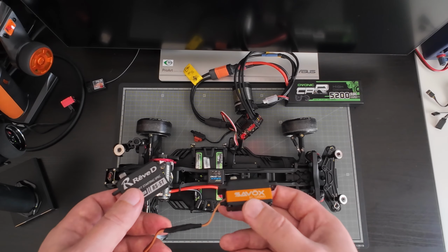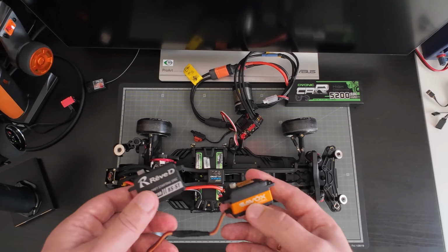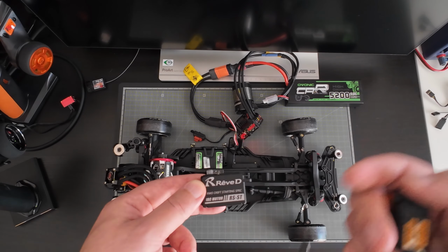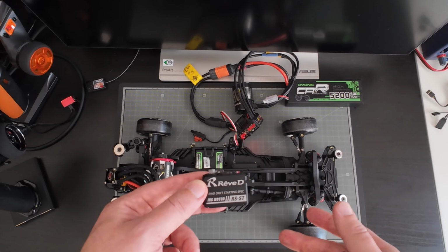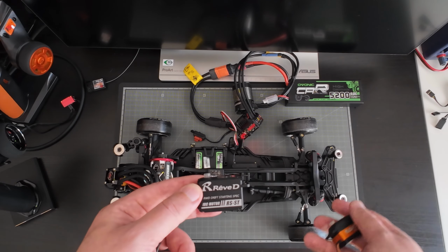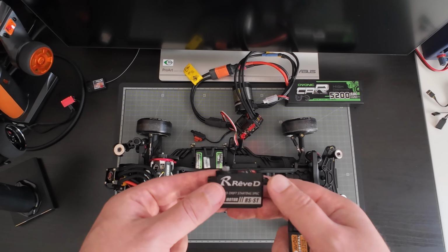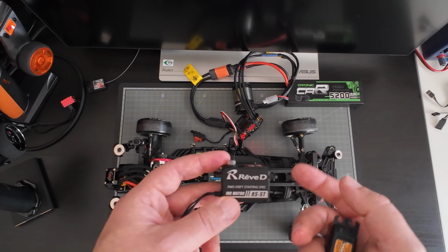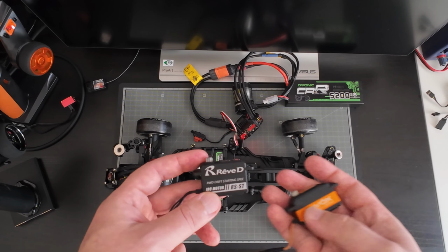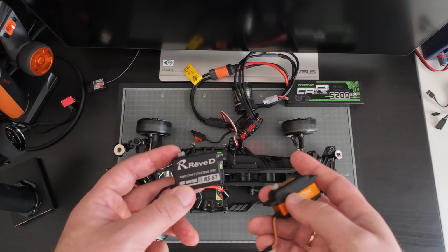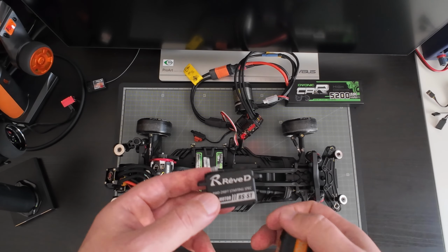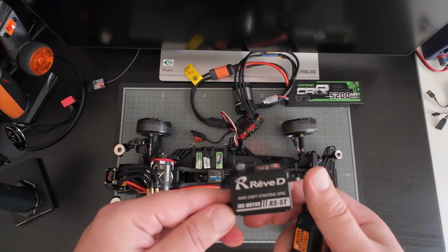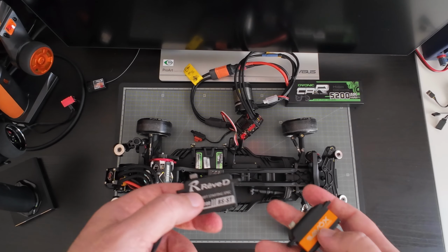Do we really need a very high speed servo in a drift car? Probably not. Where speed is important is probably on small technical tracks, where we need to turn our steering fairly quickly. On bigger, larger tracks, that's probably not the case, and that is why the original RSST works just fine. But as you can see, in the latest Rev D RSST Pro they are also using this coreless system in their servos. So they are definitely going after speed, because some people were complaining that the Rev D RSST felt a little bit slow.